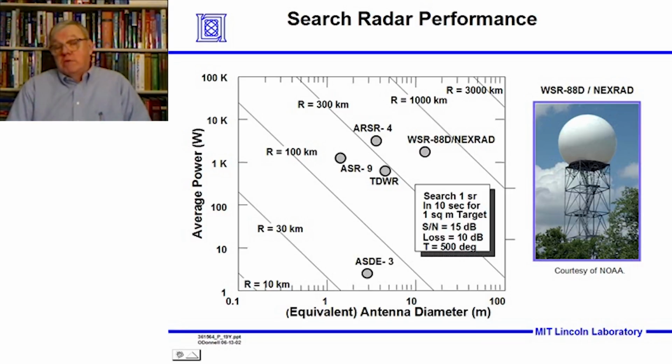S-band is a frequency that quite readily sees precipitation and echoes from weather. These radars have characteristics, which we'll talk about later, that allow them to measure the Doppler velocity of the targets they see. Their target is the rain and precipitation, a diffuse, windborne target. They characterize not only its radial velocity, by measuring the Doppler shift of the rain cloud echoes from the carrier frequency that was transmitted, but also measure the radar reflectivity, which we'll talk about as intensity.